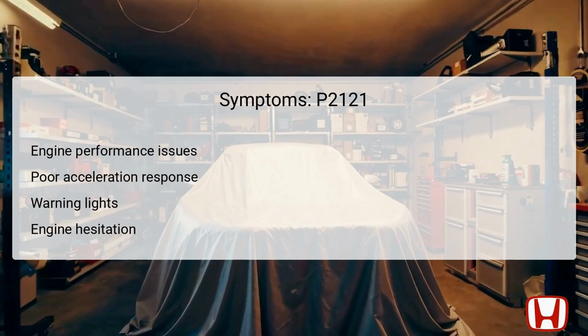Common symptoms associated with DTC P2121 include engine performance issues, such as hesitation during acceleration or an unresponsive throttle. The vehicle may not accelerate as expected, significantly impacting drivability.